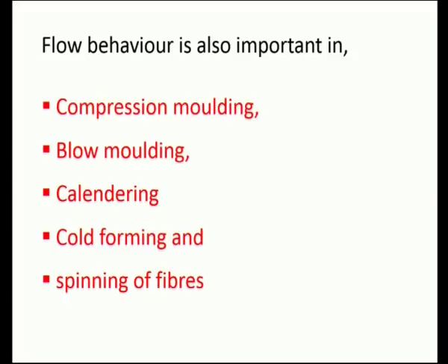Apart from extrusion and injection molding, you have other processes as well, like compression molding, blow molding, where you get your PET bottles, calendering, where you get all your adhesive tapes, and of course cold forming and spinning of fiber. Sometimes these polymers are converted into a fiber form, and later it is mixed with a polymer, and then they prepare a composite, which is what is used in aircrafts.